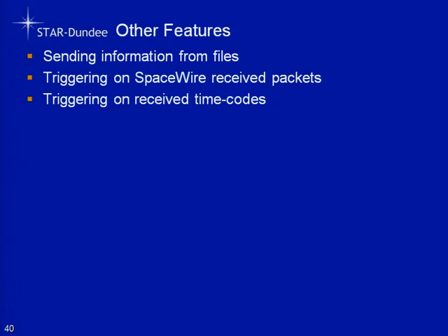So what we have is a pattern matcher. When a SpaceWire packet comes in over the link, it will do a pattern match on that. If that pattern matches, then it's going to trigger an event, and you can use that event to change state and then change the schedule that's being sent in that state and so on. There are a number of these pattern matchers. I think it may be something like 16 pattern matchers for each of the two interfaces in this EGSE unit.